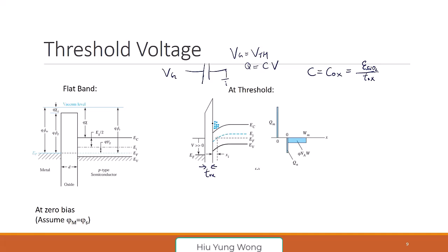Permittivity of silicon dioxide, 3.9, if you want to memorize. Of course, you still have the vacuum one, 8.8 times 10 to the minus 12 farad per meter, or in farad per cm. So it looks like I know how to find the threshold voltage, isn't that right? Is it correct that threshold voltage equals Cox, right? Because it's Q equals C times V.